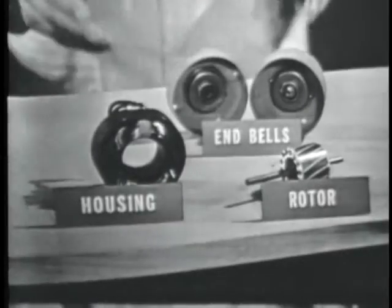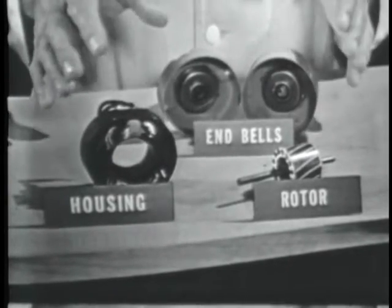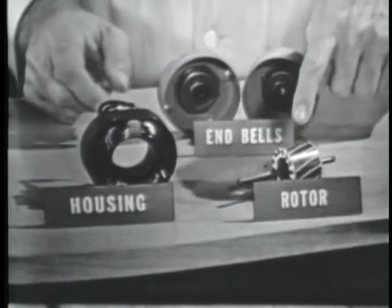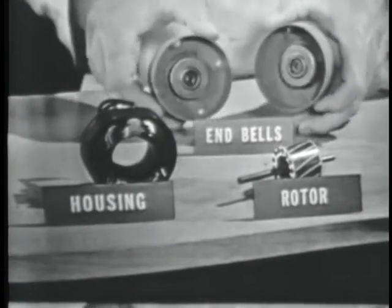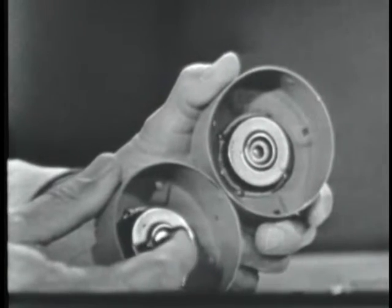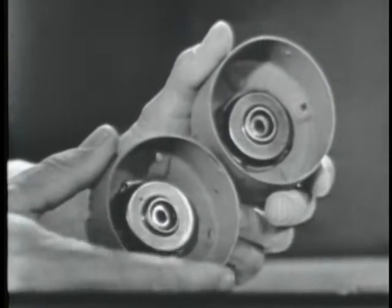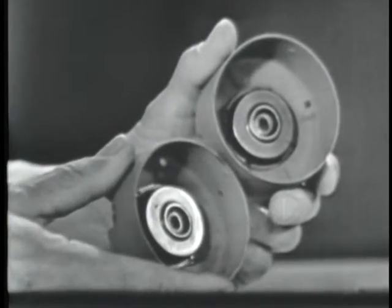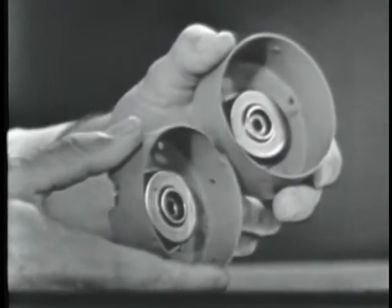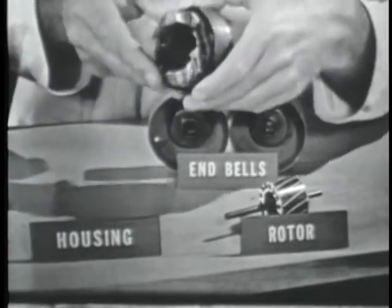This is a typical induction motor, disassembled. Now, as we've said, it's very, very simple. We have the 2 end bells, the stator field windings, and the rotor. Now, let's take a look at these end bells. The end bells are used to house the bearings or the mounting devices that hold the rotor shaft in place. Notice there are no brushes or complicated brush holding devices at all. Just simply hold the bearings. And also inside the housing, or inside the end bells, we would find the housing that contains the stator field windings.